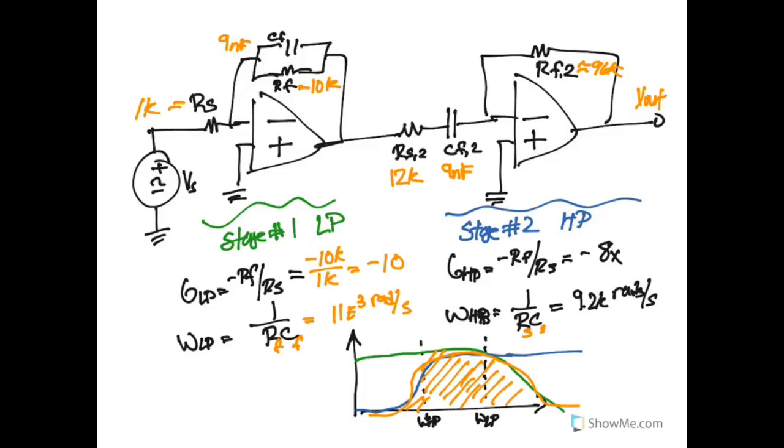And the gain on this overall is going to be greater than 1. So this result for the transfer function is going to be somewhere between 10 and 8, probably about 9, because of the gain of our op amps. So there will not be a loss in this band, and the signals within the band will actually be amplified.